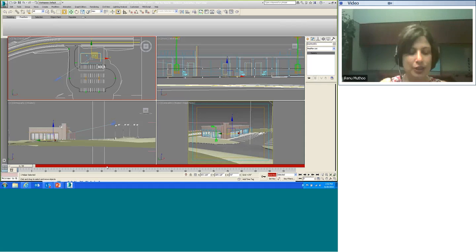So the first one, actually the second one, we will set at 33. We will just drag this slider over to frame number 33. So here we are, and at this position, we will rotate the dummy by 120 degrees because we have to get a 360-degree rotation. Because we are dividing it into 3 different keyframes, we will use 120, then 240, and subsequently 360 will be the last one, which will also coincide with the 0.